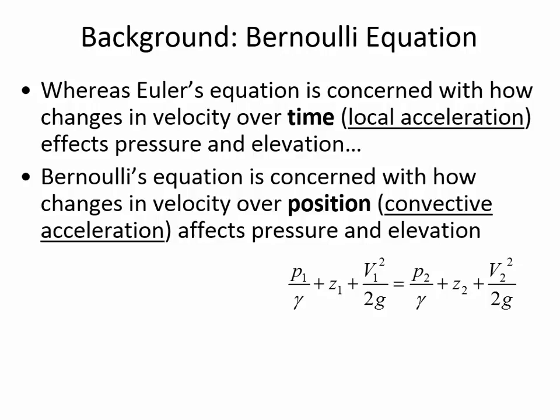Okay, so the question is, if we're applying Bernoulli's equation at the center of the pipe, you'd use the velocity at whatever location you're choosing for the point of application. And so earlier I drew, what if we wanted to do Bernoulli's equation here, where this is 1 and this is 2. We can do that as long as we're on the same streamline. The velocity near the edge of the pipe isn't going to be the same as the velocity at the center line.